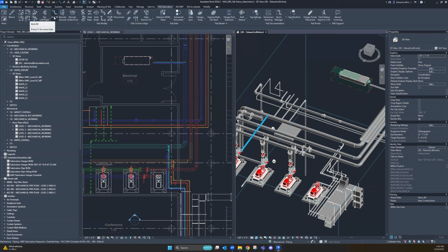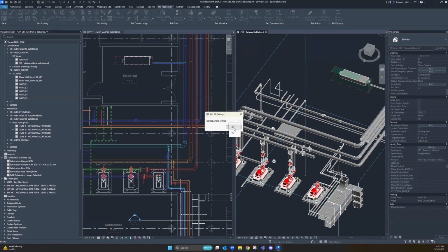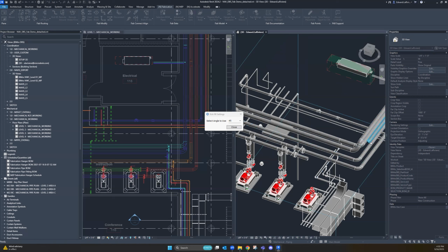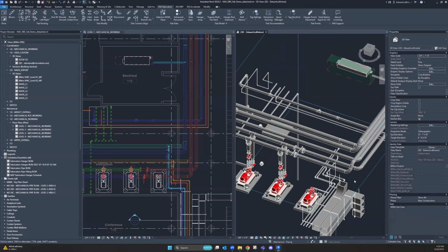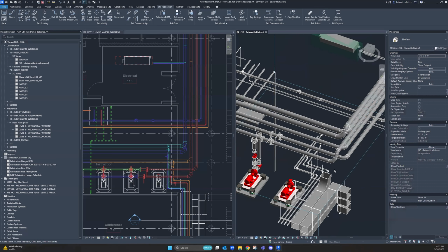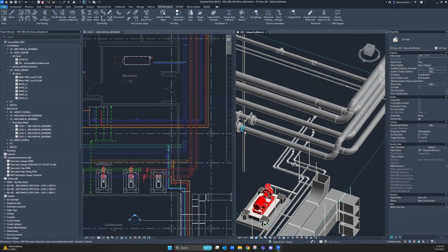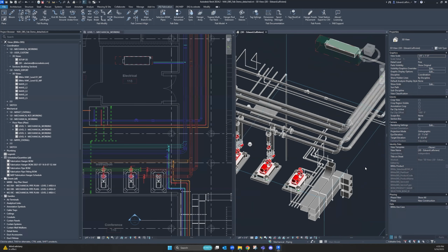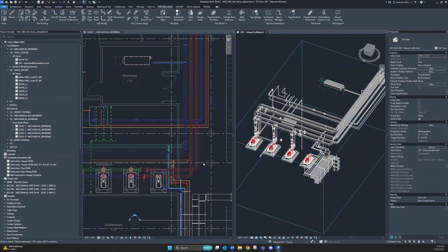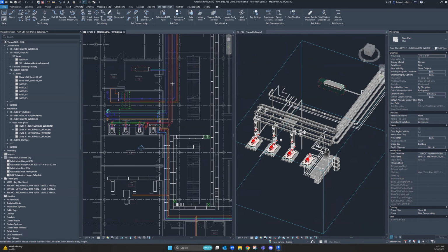So something like Kick 90 will actually let us skip that multi-step process we've done in the past. Now just calling out that 45 or 90 we'd like to work with, choosing our 90 side first and the 45 after. So if I'd like to go from a 90 here to a 45 here, we'll see we're able to choose those and have it just extend those into place for us. We'll find that this really starts to differ from that route in fill because we're not adding any extra couplings. We are just extending these over and allowing those runs to exist. So a very, very quick way for us to start getting those items modeled.